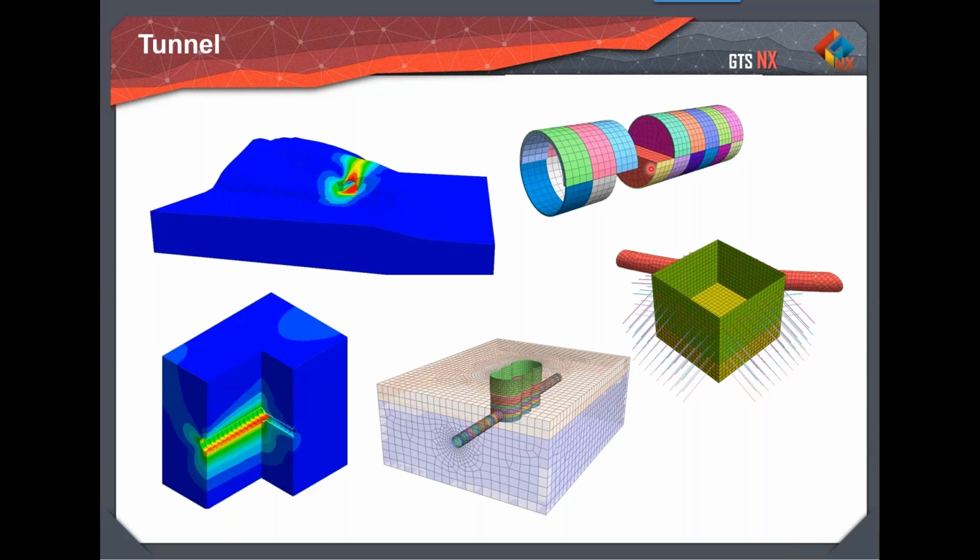And this is the NATM approach, wherein just after excavation, you're letting the soil have the residual displacement, the volume loss. You're actually letting the volume loss, and then later on you'll be applying the primary as well as a secondary lining. So that kind of simulation can easily be done.